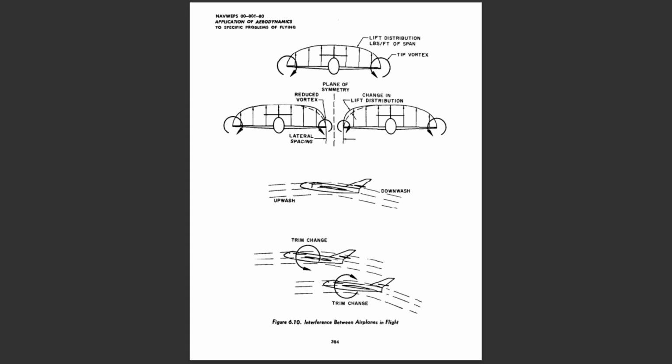An indirect form of interference can be encountered from the vortex system created by a preceding airplane along the intended flight path. The vortex sheet rolls up a considerable distance behind an airplane and creates considerable turbulence for any closely following airplane. This wake can prove troublesome if airplanes taking off and landing are not provided adequate separation. The rolled-up vortex sheet will be strongest when the preceding airplane is large, high gross weight, and operating at high lift coefficients. At times, this turbulence may be falsely attributed to prop wash or jet wash.